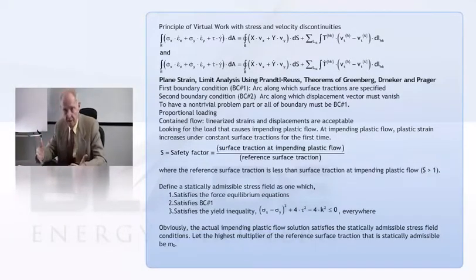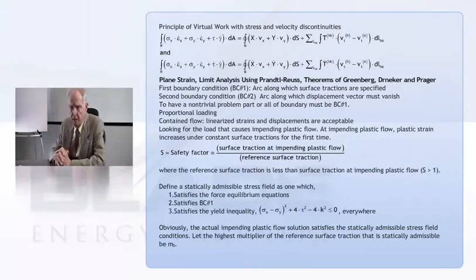So I want to just go through what these bounding theorems are, and that's what is starting on this page following the principle of virtual work equations. So first off, they only look at two kinds of boundary conditions, and they only look at the two-dimensional problem. So we're really using the same equations we were just using for slip-line theory, and we're just doing something else with them.